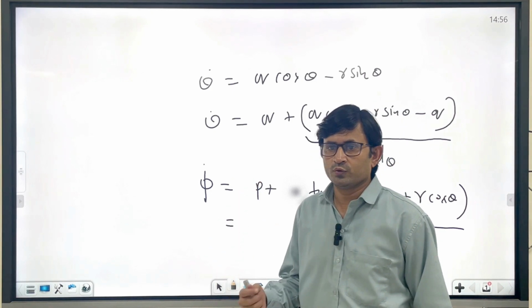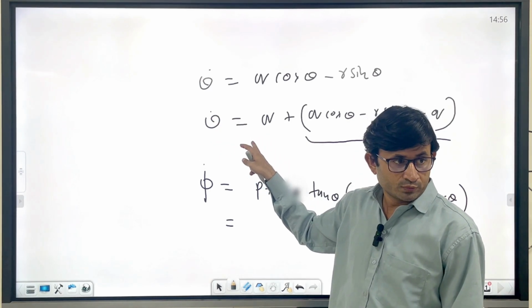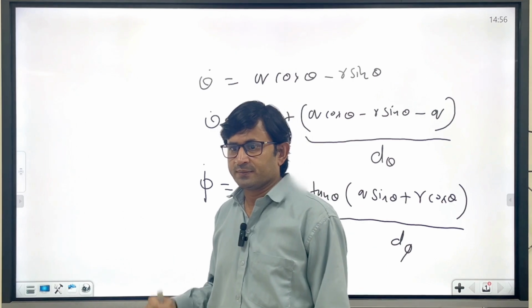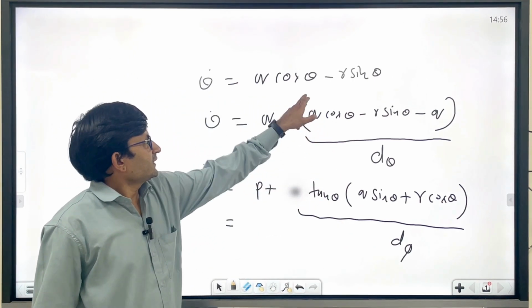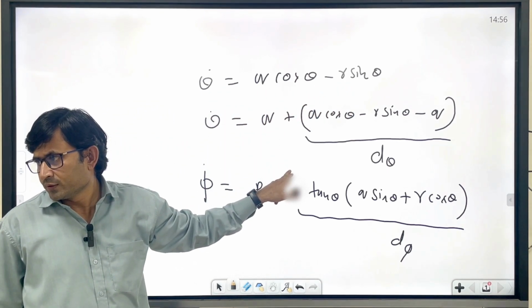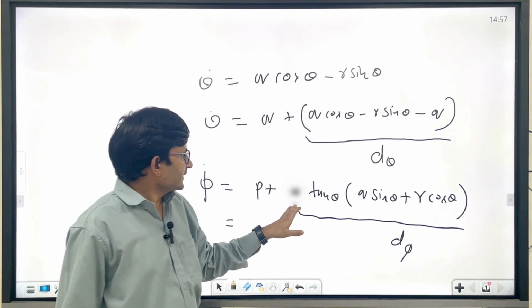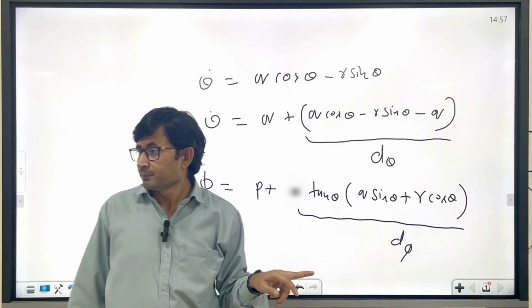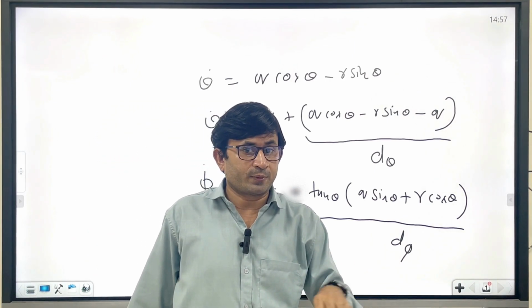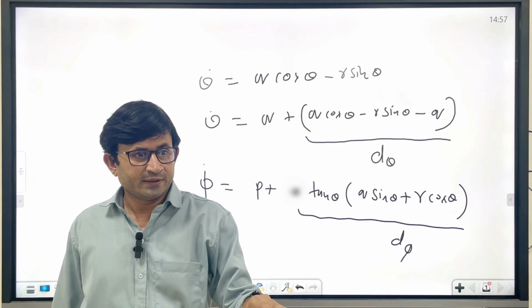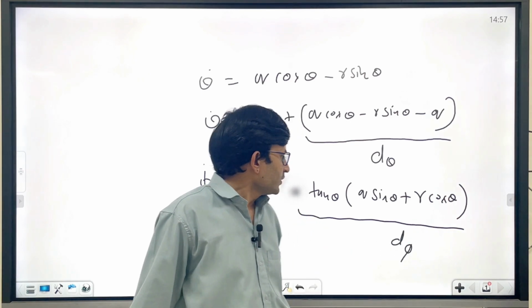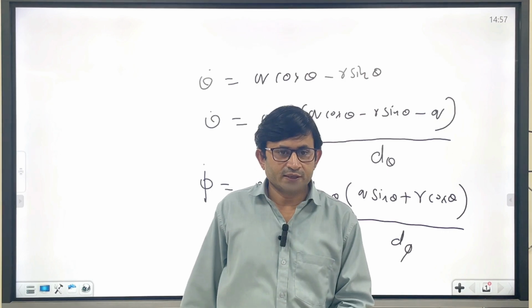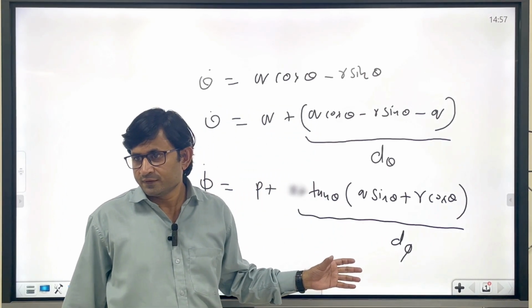So the first step is to obtain the transfer function. In the longitudinal case you make the equation theta dot equal to q, and the rest of the terms you treat as a disturbance. Similarly, phi dot equal to p, and the rest of the terms you treat as a disturbance. Why? In control design, let's say theta is small, so theta dot will be equal to q, a fair approximation. And if you have a pure roll motion, you can put q equal to 0, and you will get phi dot equal to p. In control design you approximate this, but in reality all the terms are involved, so you consider them as a disturbance, and you have to make the controller robust and powerful enough to handle this kind of disturbance.